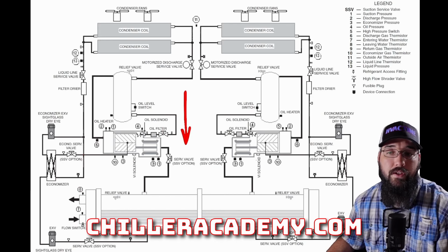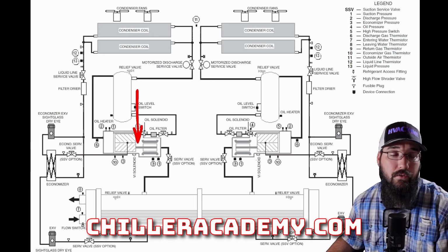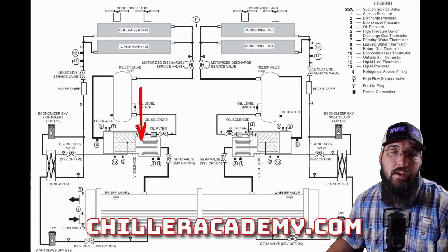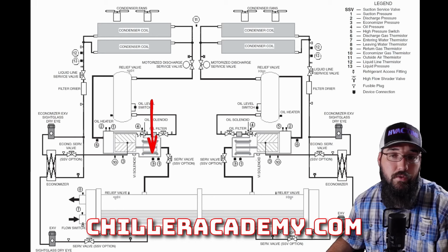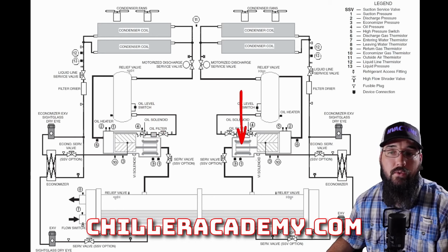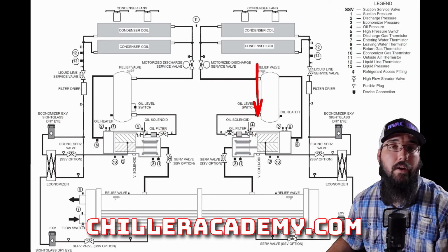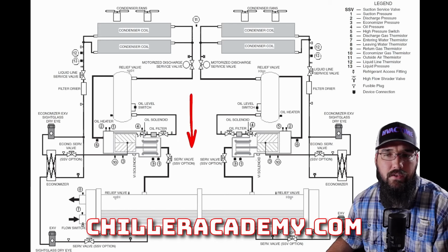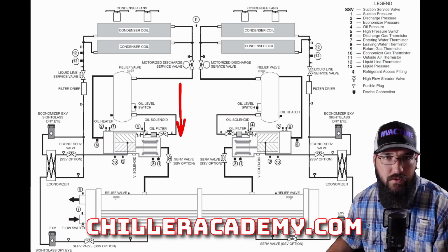And then once it gets down to the minimum loads and it's time to shut that compressor back off, say shut 1 back off, it'll turn it off in the sequence, and then compressor 2 will start to load back up. And that exact process is completely true regardless of the number of compressors.